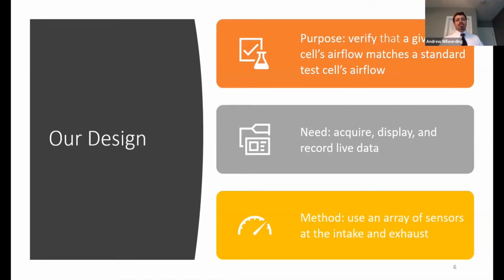So our design was to make an aerothermal test set, the purpose of which was to verify the airflow going through any given test set matched the characteristics of another standard test cell. In order to do this, we needed to acquire, display, and record live airflow data. And the most common method of doing this was to set up an array of sensors at the intake of the engine and then an array of sensors at the exhaust of the test cell. Next, please.